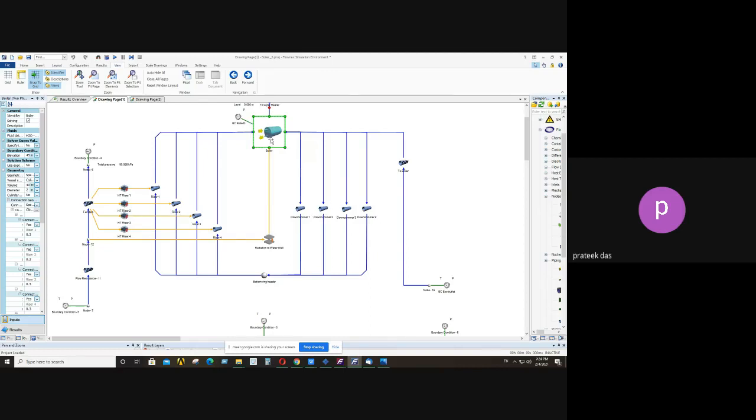Downcomers are those pipes in which the high density water flows downward due to the effect of gravity, and it is stored in this small tank. And when it is heated from any heating medium by heat exchanging with this, it eventually reduces its density. So due to this density variation, you will get a flow throughout this cycle, and this is also known as natural circulation.